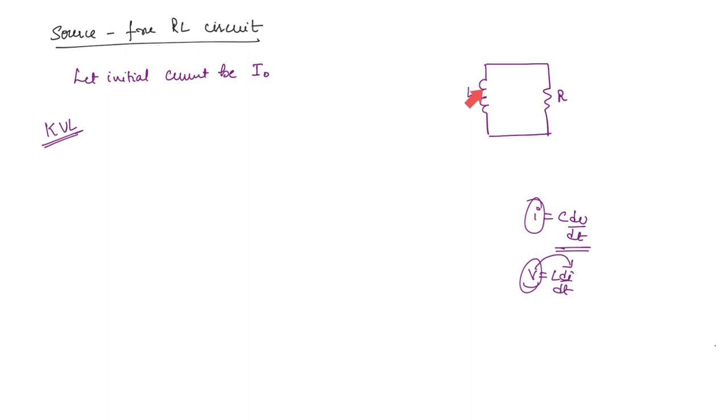So now this inductor will act like a current source. So now the current, if you take to be flowing out like this, what will be the voltage here? This will be VR. Now the voltage across inductor, you can take the positive polarity here, negative here, because the current is flowing through the positive polarity, then you can write VL is equal to L di by dt. But if you are taking positive terminal polarity here, then also no problem, you just have to include the negative sign.